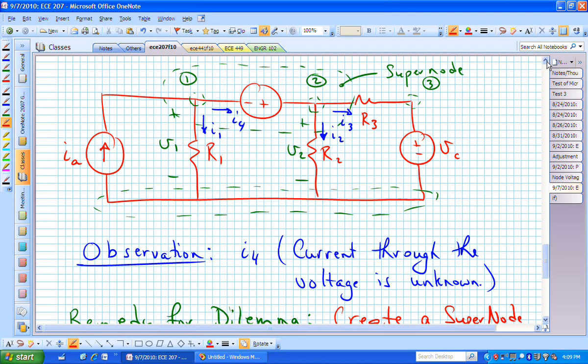If I want a current going to the right from node 2, it's the node that I'm at, V2, minus the node I'm going towards that is across R sub 3. So I now have V sub 2 minus V sub C. That's going to actually equal the voltage dropped from left to right across R sub 3. If it ends up being negative, it ends up being negative. That's okay. Doesn't really matter, but my formulas will be correct and they will account for that.